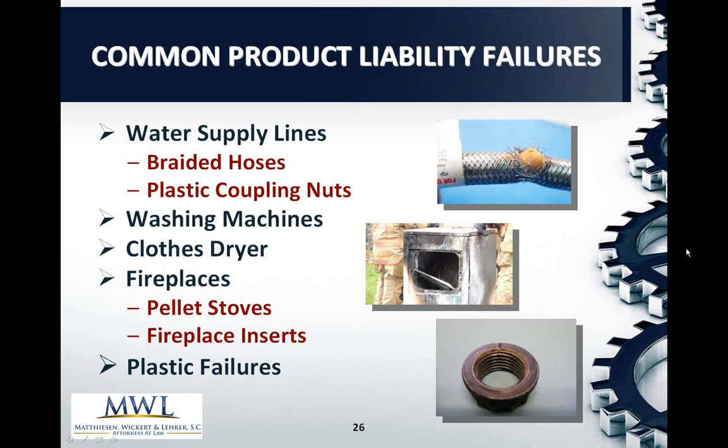Fireplace inserts, a lot of times you'll see that the clearances weren't taken care of too. A lot of times, you need at least an inch or so of clearance. Codes kind of vary on that, but if an insert isn't sized correctly and it's in touch with a wood stud or a piece of insulation, it may not start a fire right away, but over time the heat's going to build up to the point where a fire will start.